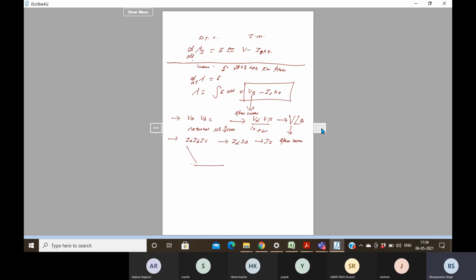If you have three currents Ia, Ib, Ic, they can be equivalently converted to I alpha, I beta in the stationary reference frame, which is equivalent to some vector I at some angle theta. Or you can say that the resultant air gap magnetomotive force F is assumed to be produced by this single space vector Is.